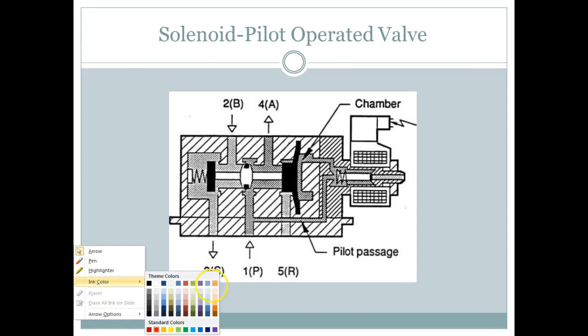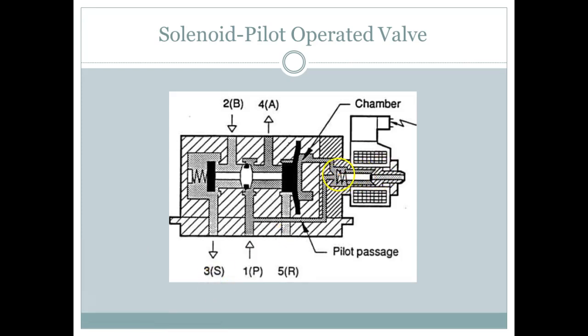Well, what they're showing me right here is the solenoid, but all the solenoid does is move this little old plunger. Now here's pressure sitting right there, ready to move the spool. If we follow this little path, it comes over to right there. So when I energize the solenoid, it pulls this thing back. Then the actual pressure comes over here and pushes the spool. So here we can have a tiny solenoid because it's controlling just a very small flow. That's all it's doing, right?